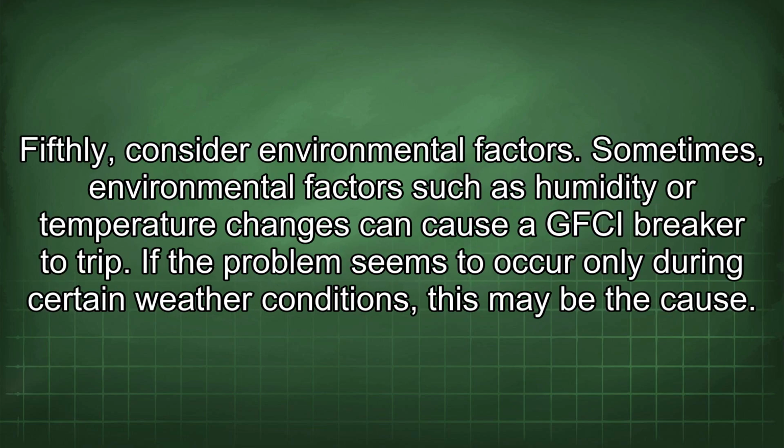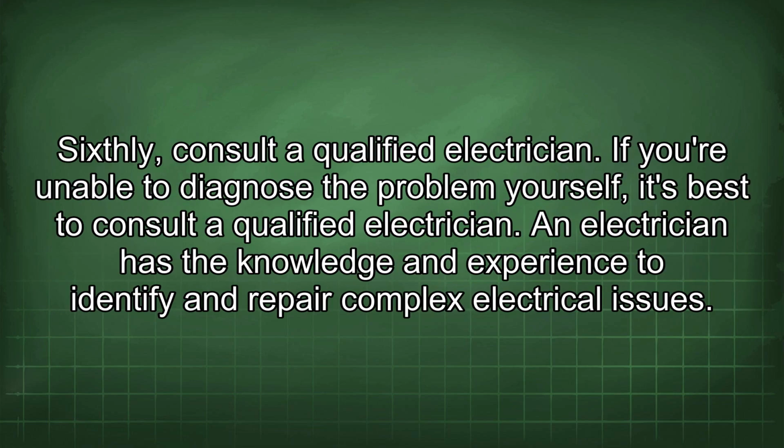Fifthly, consider environmental factors. Sometimes environmental factors such as humidity or temperature changes can cause a GFCI breaker to trip. If the problem seems to occur only during certain weather conditions, this may be the cause. Sixthly, consult a qualified electrician. If you are unable to diagnose the problem yourself, it's best to consult a qualified electrician. An electrician has the knowledge and experience to identify and repair complex electrical issues.